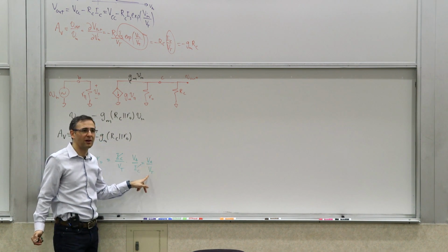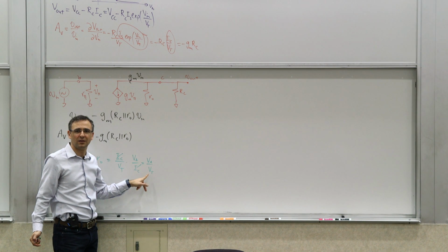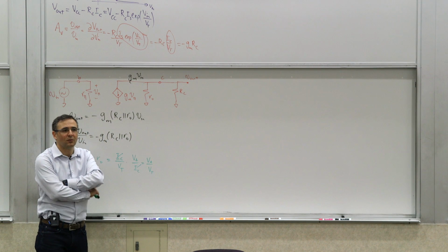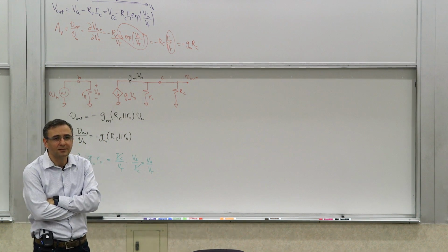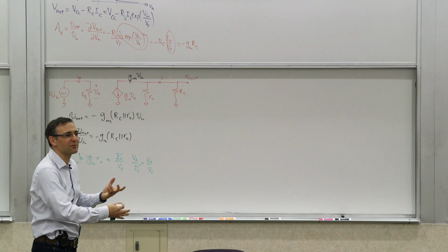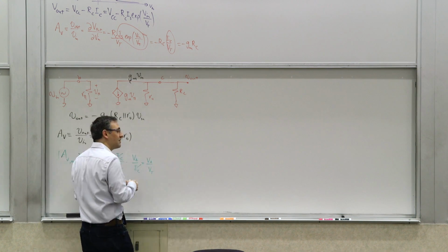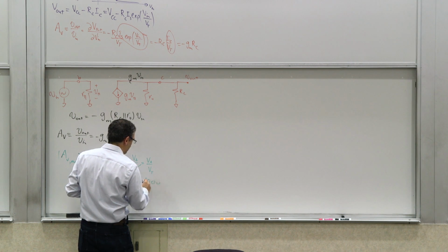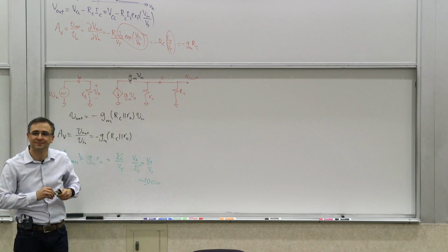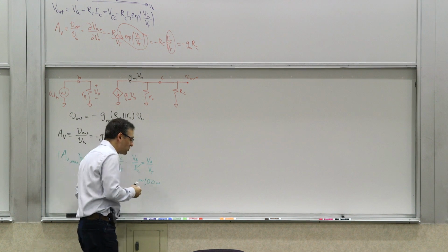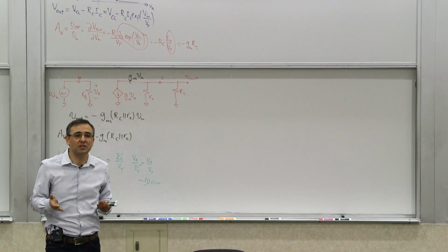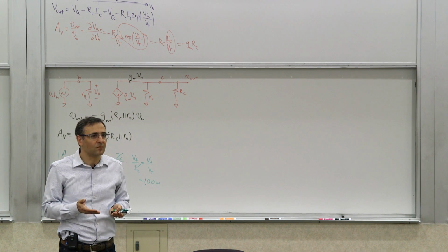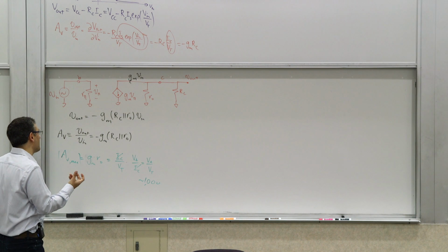So that's 100 over 25 millivolts. What is 100 over 25 millivolts? It's 100 times 40, 4,000. It's in the thousands, right? I mean, high hundreds to a few thousands. So let's say in the range of thousands. And of course, this changes from one transistor to another, so this is somewhat of an intrinsic property of a transistor.